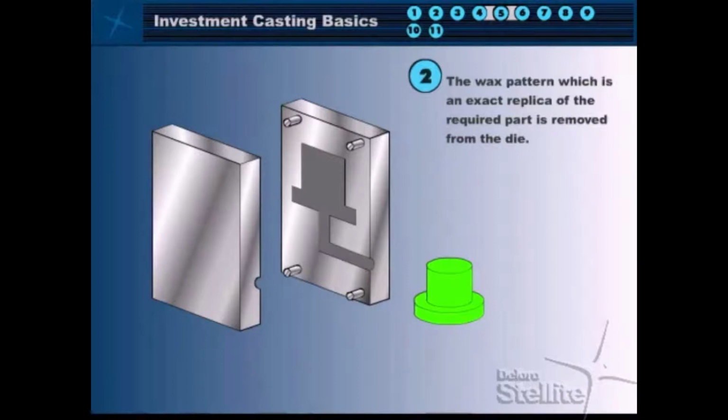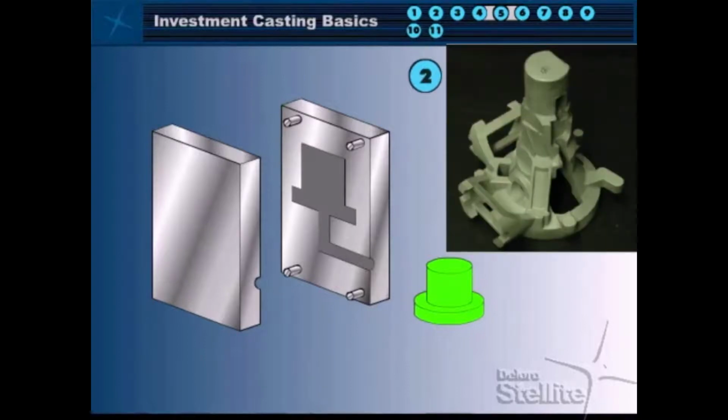So there are two contraction rates that have to be designed into the tooling, and pattern maker's contraction is a concern in the design of the tooling to make sure that the dimensions, although extremely accurate, are centered within the specified tolerance band. In addition to the accuracy of the ceramic shell investment process, the complexity of castings that can be made in the process is very significant.